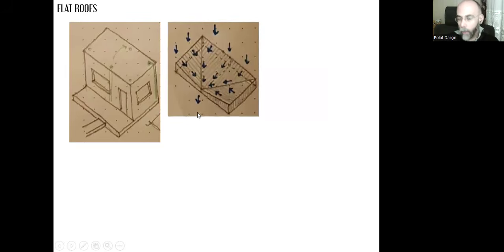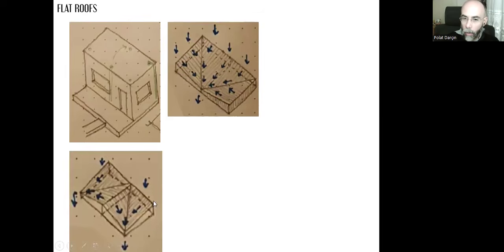Or if we want to collect all the water at a single point, then again, we can divide it into squares like this. This first part will direct the water towards this valley. The other part will direct the water towards this valley. And the third part will direct the water towards this drainage. We cannot always do it with a single pipe, because it depends on our facade design as well. Maybe there's this window or door where we cannot place the downspout. That will be a problem.